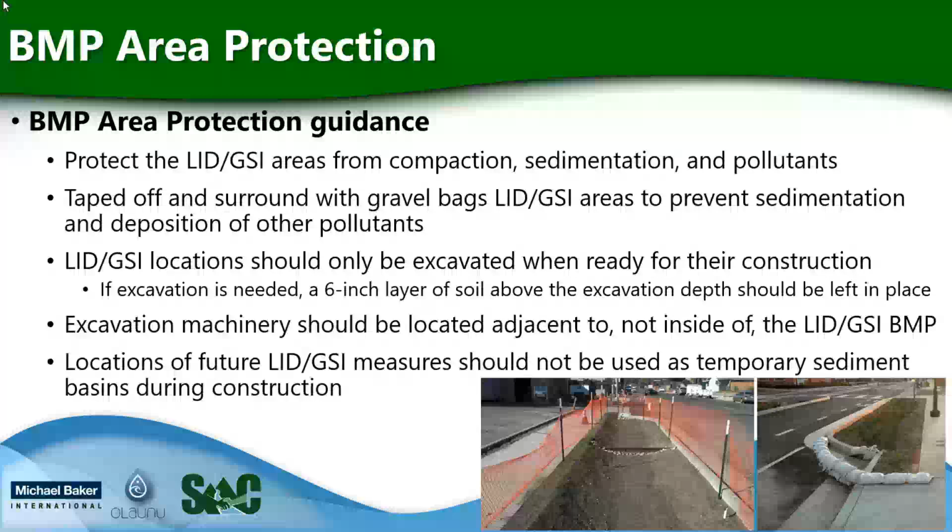Additionally, LID and GSI locations should only be excavated when they're ready for construction. If excavation is needed prior to that, a 6-inch layer of soil above the excavation depth should be left in its place. Excavation machinery should be located adjacent to and not inside the LID and GSI system. That equipment will cause compaction and reduce the infiltration rate of your LID and GSI systems.